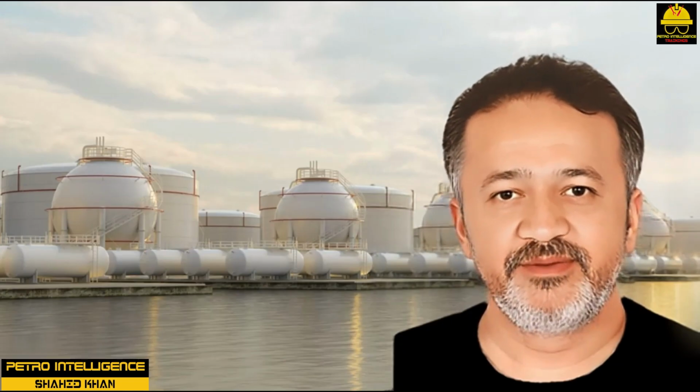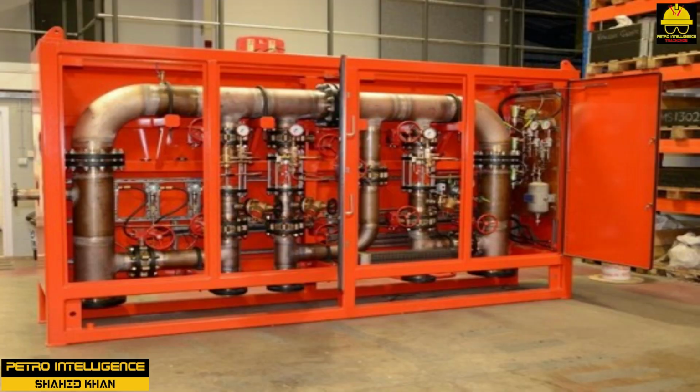Copper alloys. Brass is the term used to describe a family of alloys of copper and zinc. The copper content ranges from 90% to about 60%, with the balance being zinc. Some brasses have small amounts of other elements such as lead, tin, antimony, arsenic, and phosphorus.